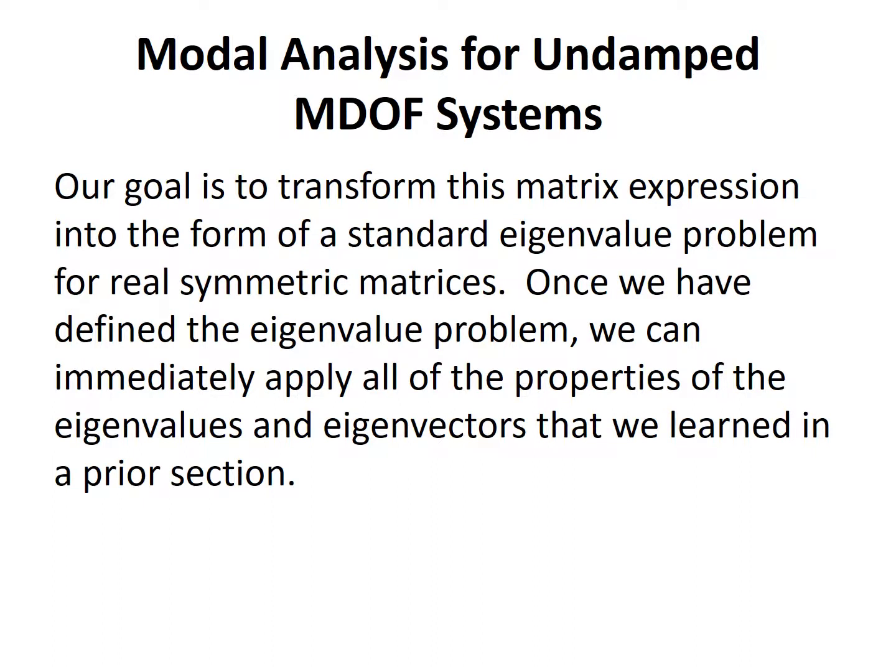In this lecture, we will demonstrate how the solution of the undamped multi-degree of freedom vibration problem can be related directly to the solution of an eigenvalue problem for a real symmetric matrix. Once we have cast the problem in this form, we will immediately apply the properties of eigenvalues and eigenvectors to transform the problem into the solution of a set of single degree of freedom oscillators. Each single degree of freedom oscillator can then be solved independently, and the solution in modal coordinates is then transformed back to physical coordinates to obtain the solution of the original matrix differential equation. This process is called modal analysis.